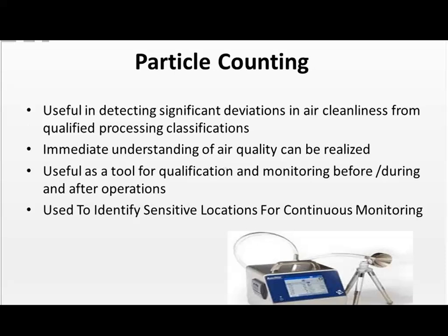We can use particulate monitoring as a tool for qualification. We can monitor before and after operation. And when we're starting up a clean room, it's very important, and my suggestion, to monitor particulates before and after an operation and also during the operation, because you want to see what your room is at a clean, static condition.